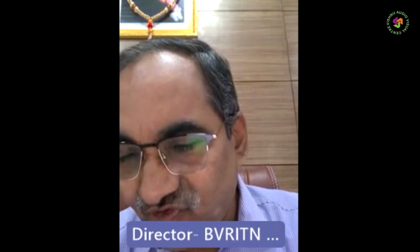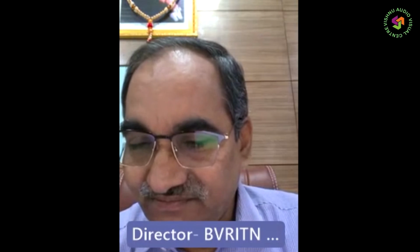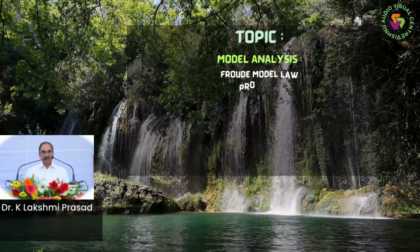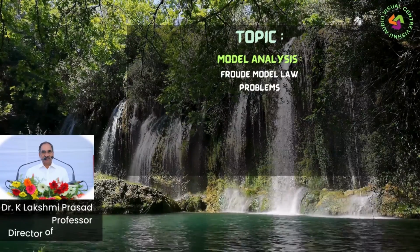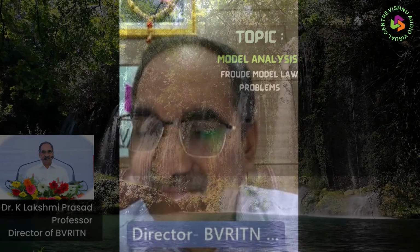So in order to simplify that problem, we have defined the dimensionless numbers. The dimensionless numbers are nothing but the ratios of the forces. And the dimensionless number signifies which force is significant, which force is really useful in a particular problem. So after defining the dimensionless numbers, in order to achieve the dynamic similarity, we have defined the model laws. There are five model laws, out of which the Reynolds model law was taken last time in the previous lecture.